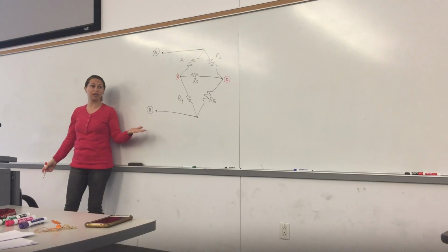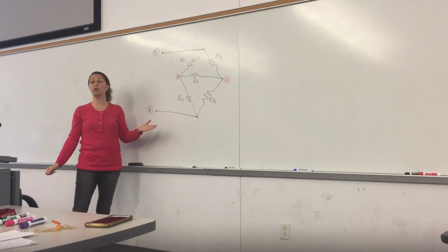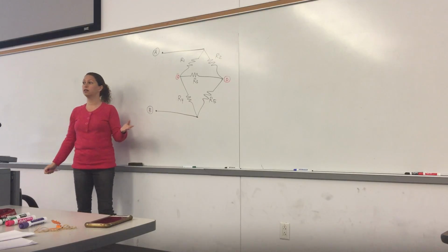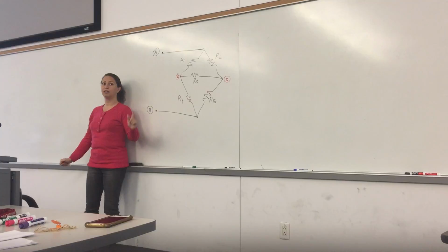Anything in parallel? Not really. Anything in series? Yeah. Where? Well, R1, R2. R1, R4. R1, R2, are they in series? No. Why? They end up in different wires.